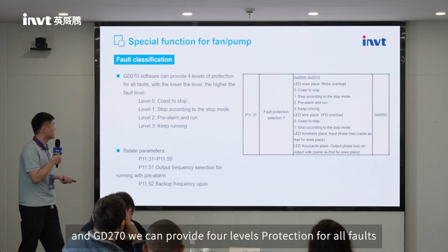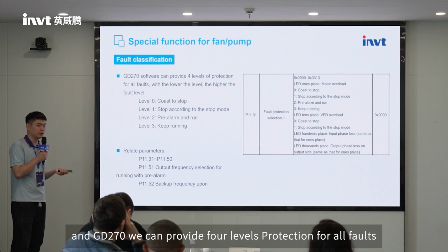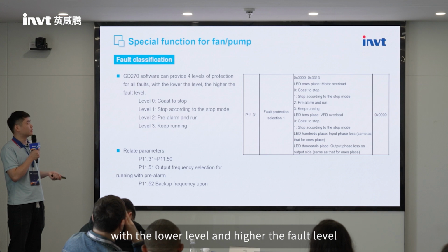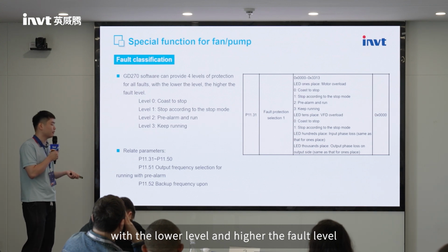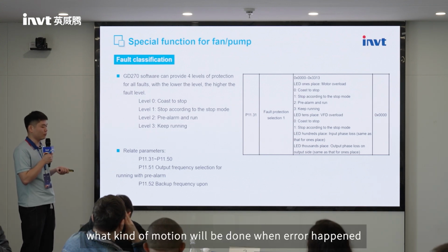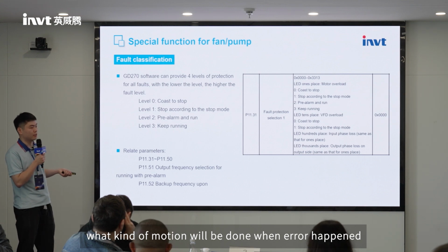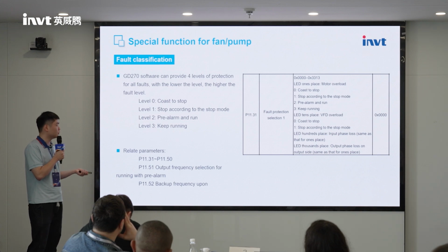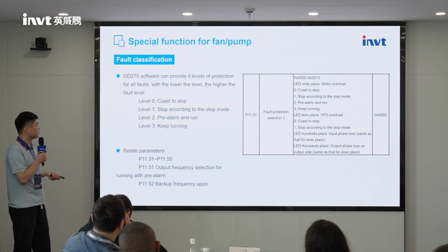And the GD270 software can provide 4 levels of protection for all faults, with low level and high fault level. You can choose what action to take when an error happens: stop according to a stop mode, press alarm, or run and keep it running.